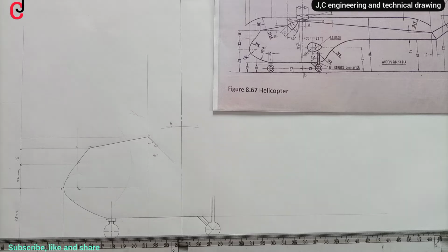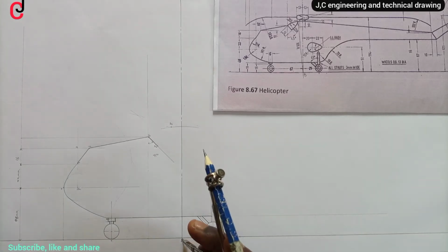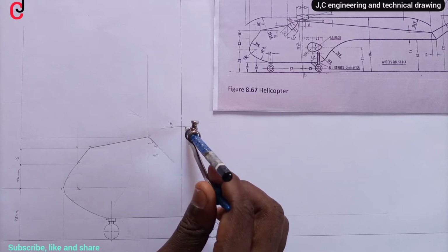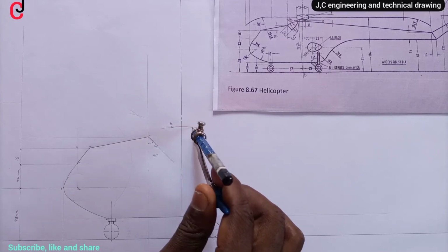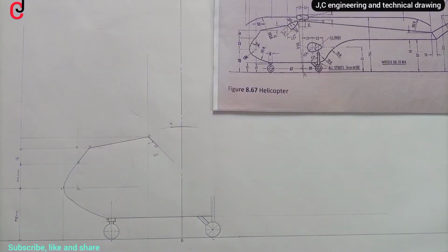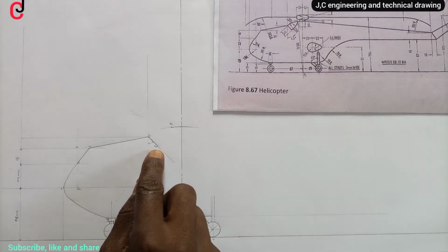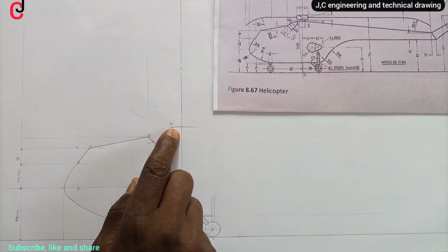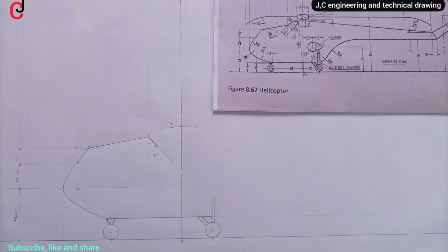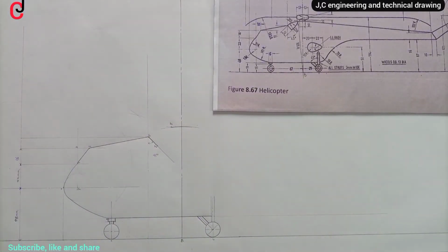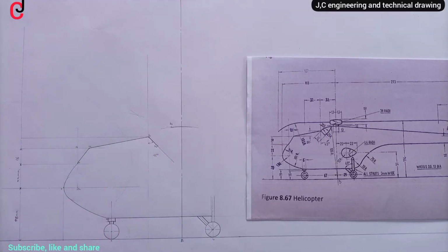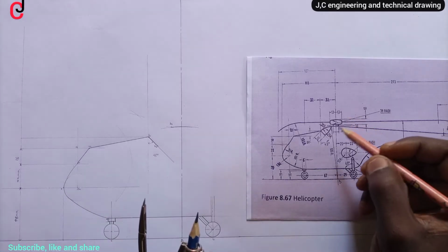Then we are free to outline our arc because we now know where to outline that portion. Now using points B2 and point B3, we'll open our compass to 38 millimeter radius. This is it from our diagram.